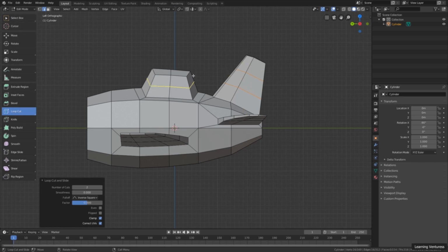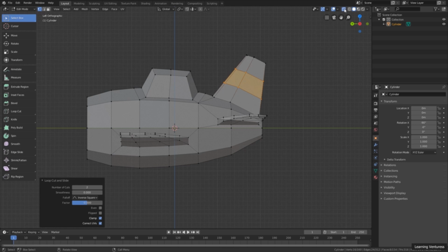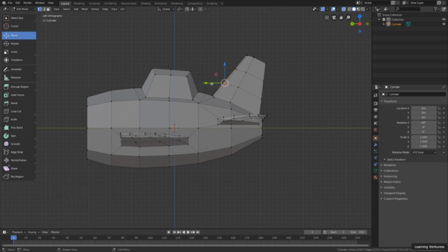So to do this, I will activate the select box tool to select the vertices from both sides, and activate the vertex selection mode. And I need to activate the X-ray mode so that I am sure that when I select things from one side, the vertex on the other side are also selected. Okay? So now I can create a selection window to select these vertices here and move them forward a bit on the y-axis.